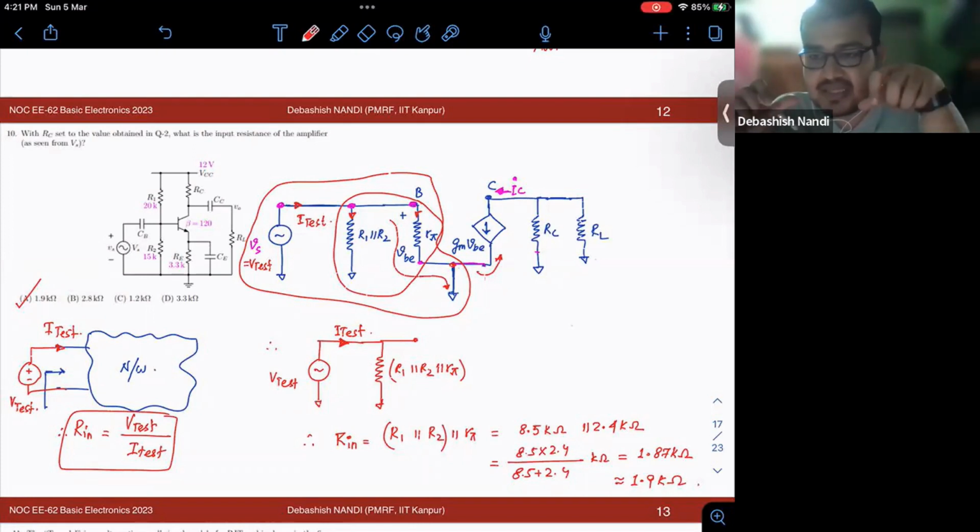First analyze the DC biasing conditions and see whether I am in saturation, whether I am in active, when I am in active, when I am in saturation, when I am in cutoff. Then you move on to the AC analysis, see the gains, see how the capacitances are playing and limiting the frequencies, right? You do it for 2 or 3 circuits, and let me tell you, you will be very good at this circuit analysis. Okay.